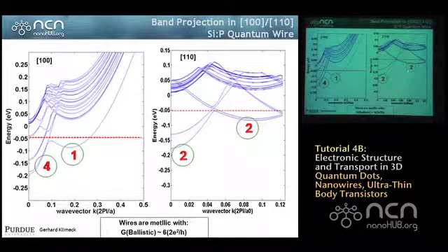Interestingly enough, the conductance is roughly the same. It's 6. There's 6 bands that run through the Fermi level. Yeah? So why is the Fermi level using the conduction band rather than the valence band? The boundary condition is that we say we have 2 impurities and therefore we have 2 free electrons. So we force the system to have 2 electrons, so it's charge neutral. For it to be charge neutral, these bands need to flow down to minus 200 or so, versus 0 is always the reference of bulk silicon, and the Fermi level needs to occupy to there.